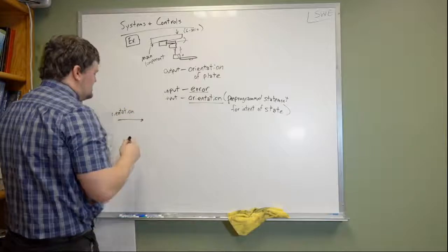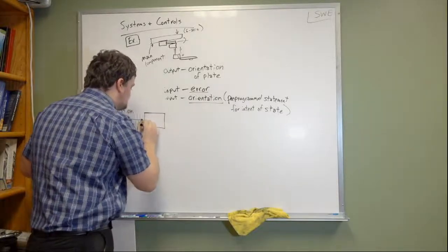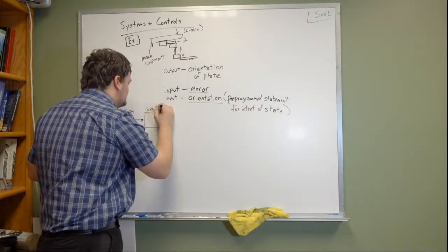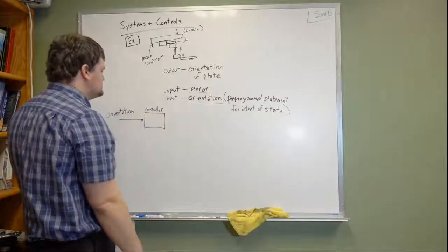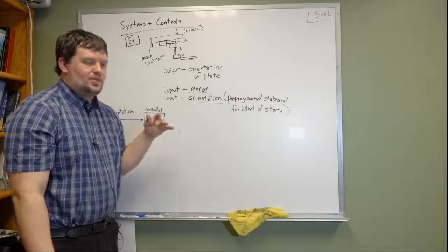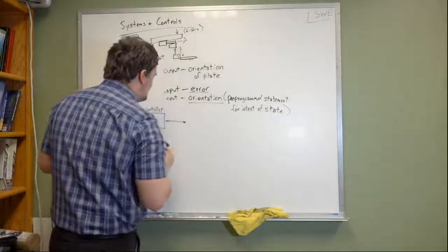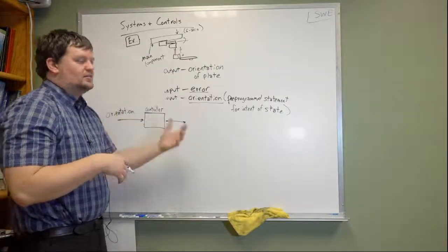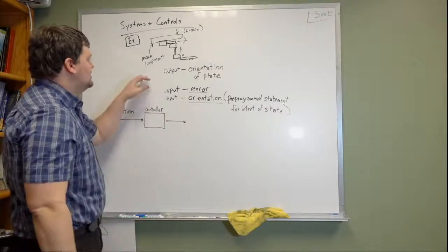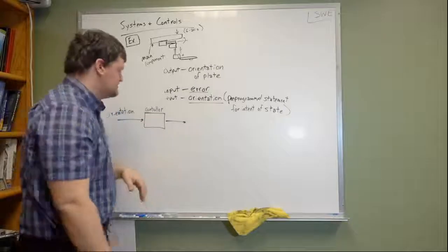This pre-programmed orientation value, stored on the controller, goes into the controller, and the controller says, all right, based on what I want this orientation to be, I'm going to output a voltage value that will control the servo motors, the 3 servo motors here that are controlling this very simple gimbal.